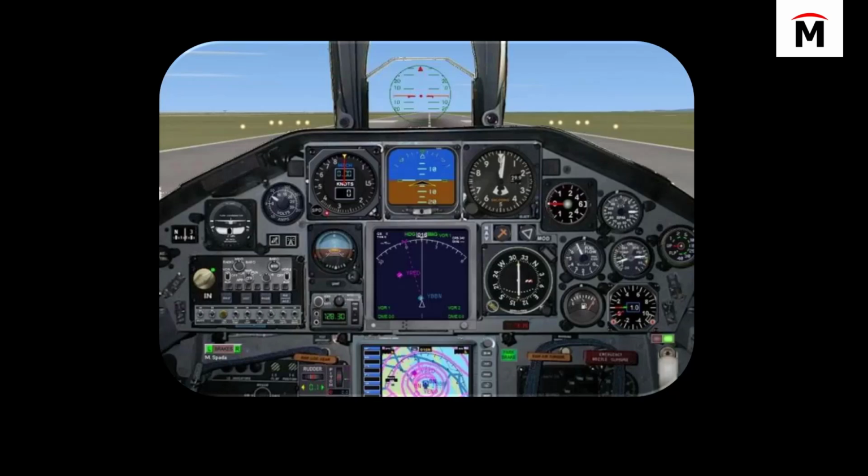Another thing I see is we'll hit too many buttons all at once and kind of lose track of where we're at. I'll sometimes just go restore from default and then start my tool axis control, my drive surfaces, and everything over again from the start, and pay attention to what variables I'm actually changing.